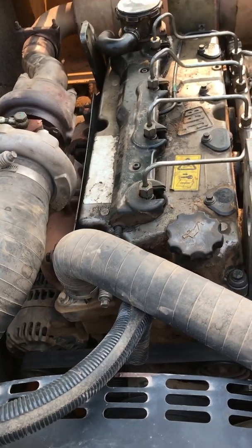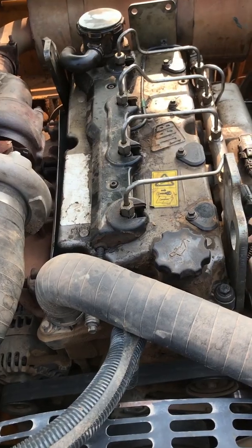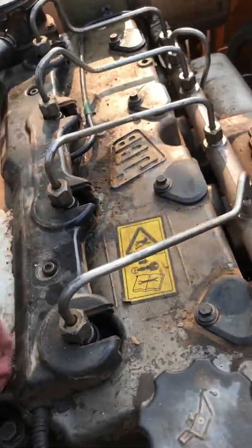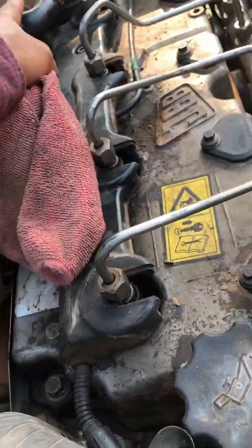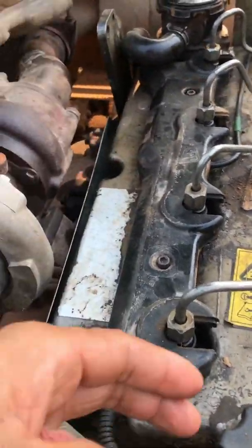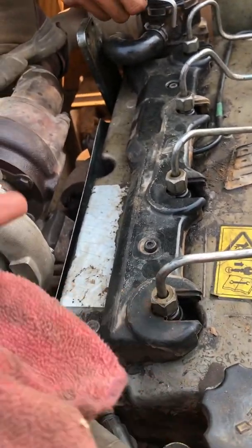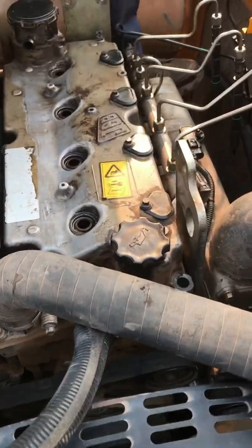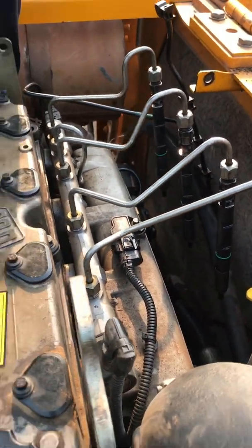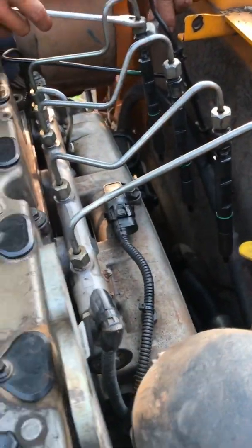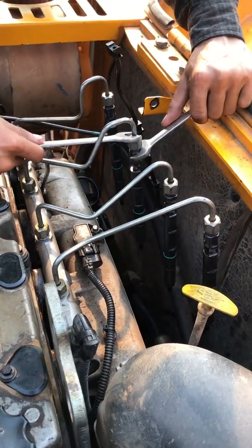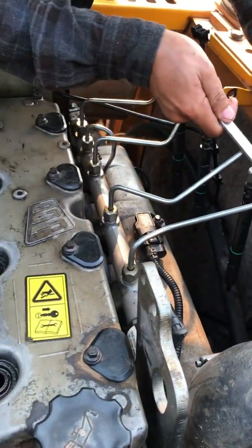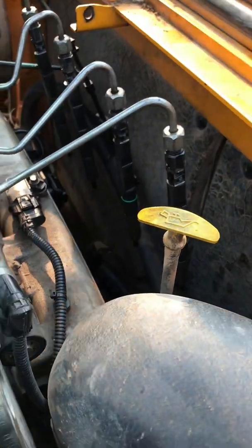So right now I will do the injector test on the machine. So I have to take out the injector from here. Take out this pipe, 1, 2, 3, 4, and then 2 screws, take them out, and this hose, remove it, then remove this rocker cover, the top cover, then we can remove the injector holder. Okay, so right now I will test the injector on the machine, connecting like that. I use all of the pipes. So I put it on the machine common rail, use each pipe, and also I will use the engine wire harness to connect to the injector.